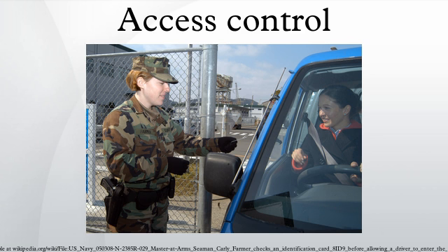A wide range of credentials can be used to replace mechanical keys. The electronic access control system grants access based on the credential presented. When access is granted, the door is unlocked for a predetermined time and the transaction is recorded. When access is refused, the door remains locked and the attempted access is recorded. The system will also monitor the door and alarm if the door is forced open or held open too long after being unlocked.